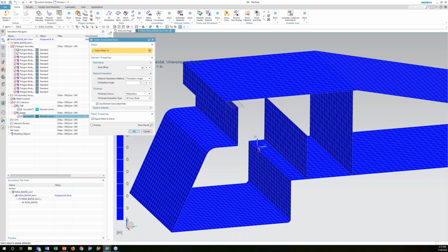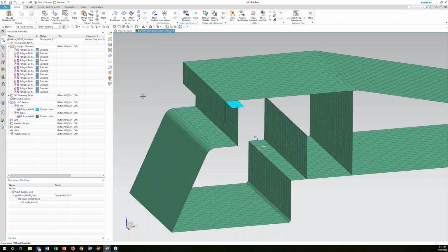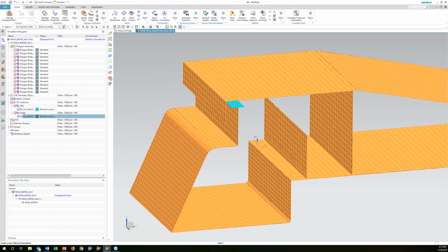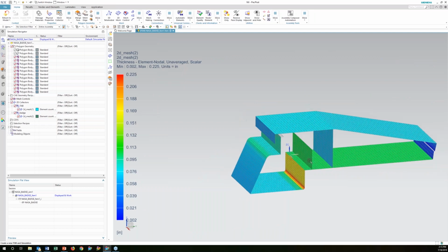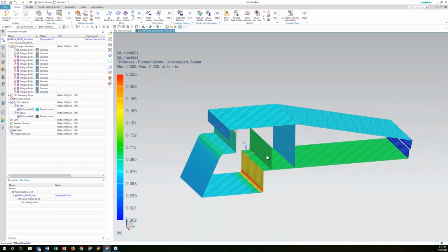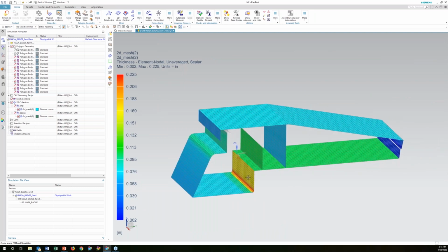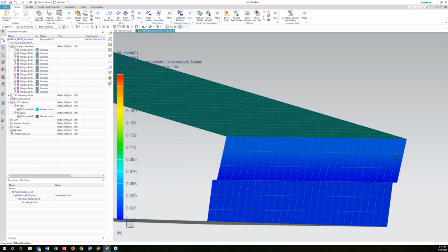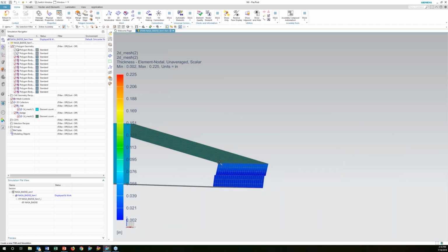And now if we go ahead and plot those thickness and contours again, now you see that we have those varying thicknesses throughout the structure. And it's not just one simple value here. I don't know if you remember from the geometry, this part was actually thicker than the rest of the structure. And even if we zoom in pretty good down here, you'll notice that we do have a gradual taper, because this is how the part has been set up as well. And the tip of those entities are the thinnest portion in the model, which makes sense based on how the geometry was.